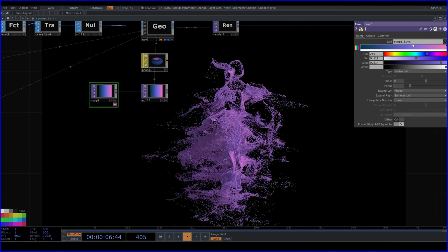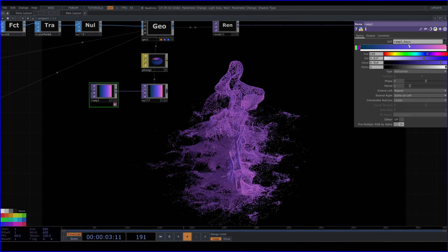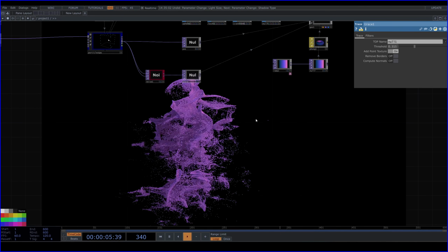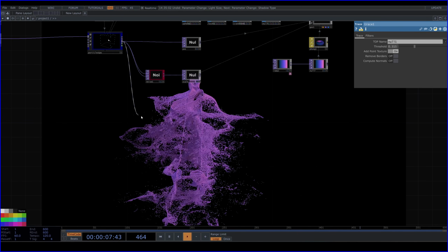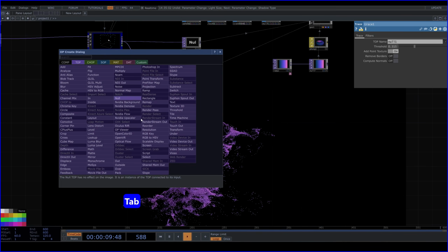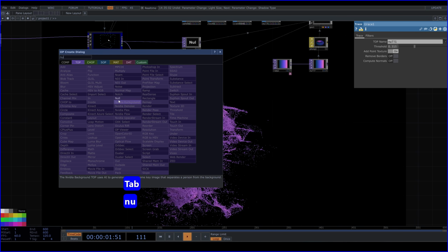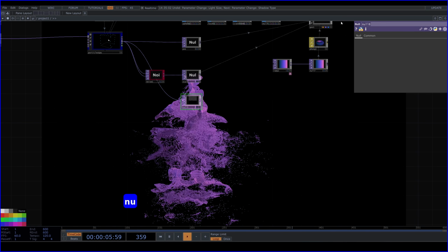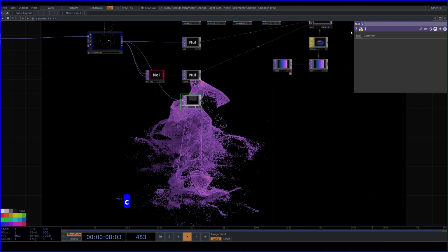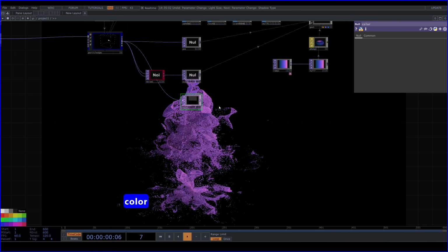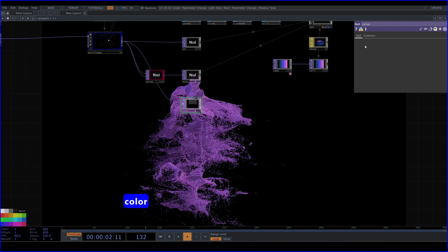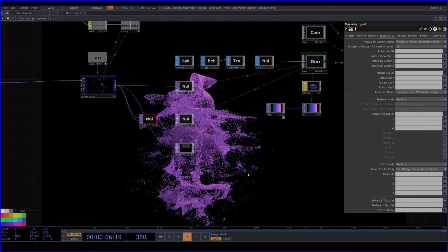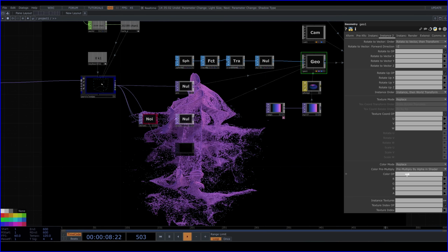So besides using a ramp TOP to put on the color map in the phong material, we can do another method of colorizing the particle. Let's create another particle position output that we will use for color instancing. At this instance page, we add this to color.